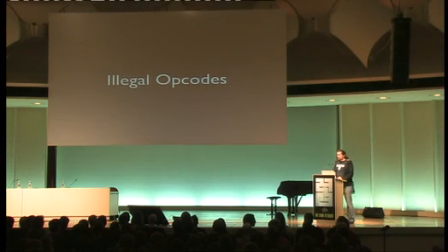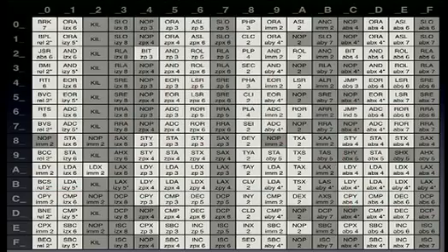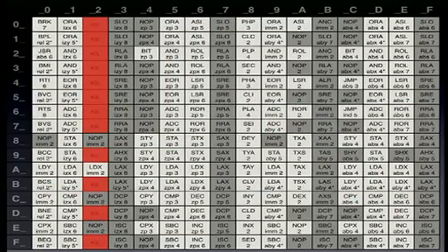So now this is illegal opcodes. These are the holy grail of understanding the 6502, and I think we have made some progress there. What people have done so far is mostly, well, measure them and see what they are doing. And there were some theories that they seem to combine the ones that are close to them, but now we can say a lot more about them. So the kill opcodes, for example, most of them that end in 2, they just halt the machine. Reset still works, but IRQs and NMIs won't get delivered.